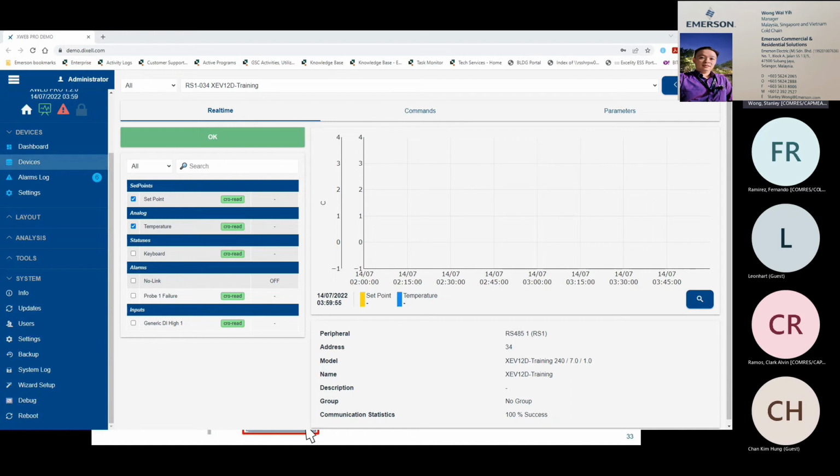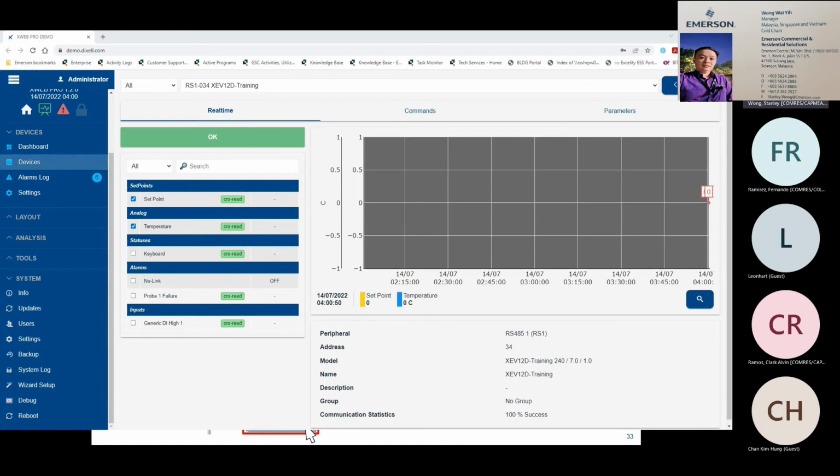Let's say if it is to do a third-party Modbus device, probably a BTU Modbus meter, is it also the same method that is applied? Yes, you would use the same method, because they would use the same types of registers. The only difference would be the format that other companies would use. So it might look a bit different.